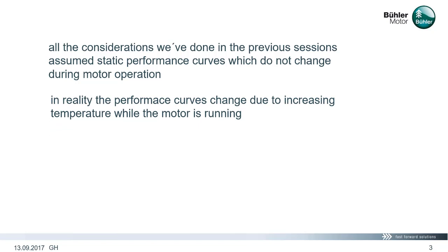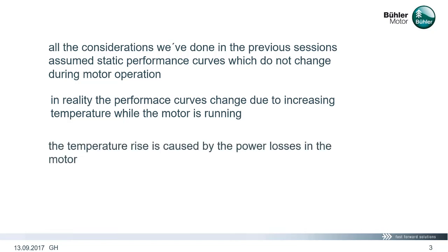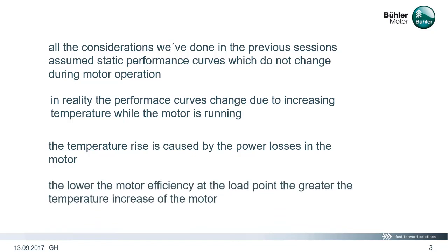In reality, though, the performance curves change due to increasing temperature while the motor is running. The temperature rise is caused by the power losses in the motor, which are completely transferred into heat. This means the lower the motor efficiency at the load point, the greater the temperature increase in the motor.